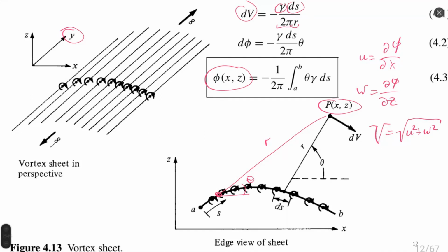And to obtain pressure, we use the Bernoulli equation, which relates velocity and pressure. So when we know velocity, we calculate pressure. This is it. And then pressure enters inside the CP coefficient, inside the calculation of lift. And I think we already saw these equations before, and soon we will see them again. So no need to write them right here.